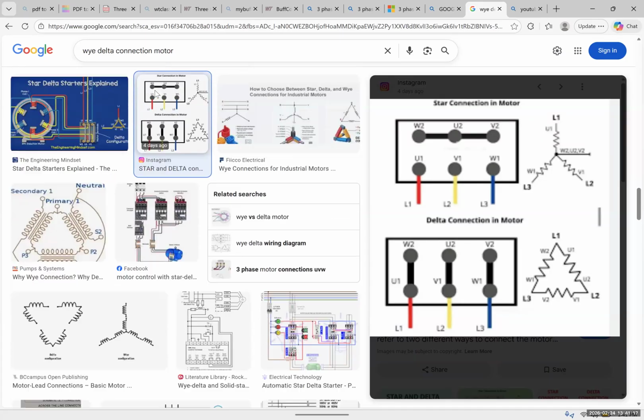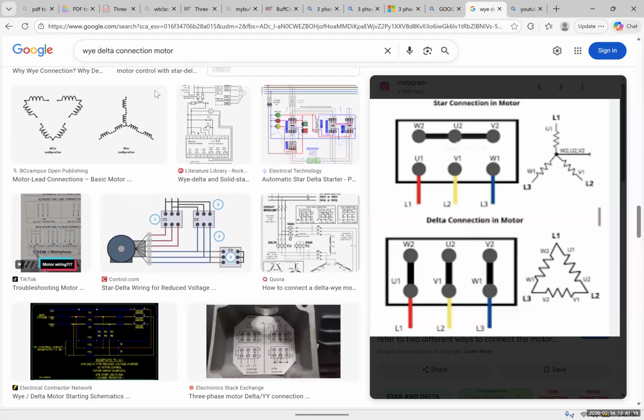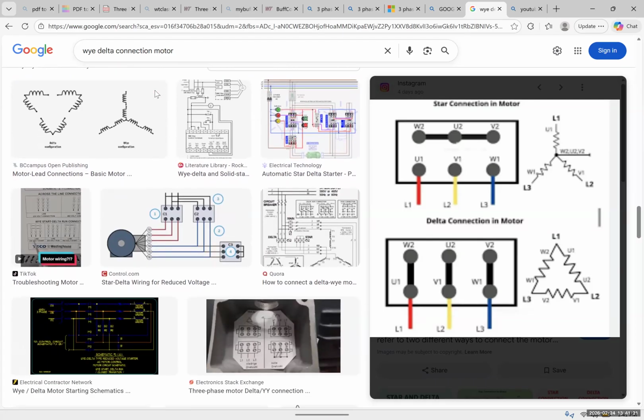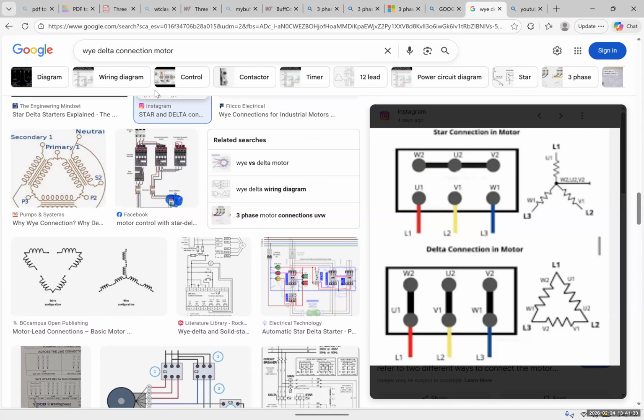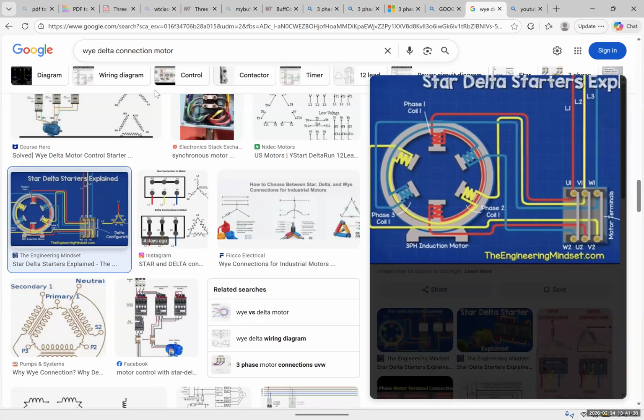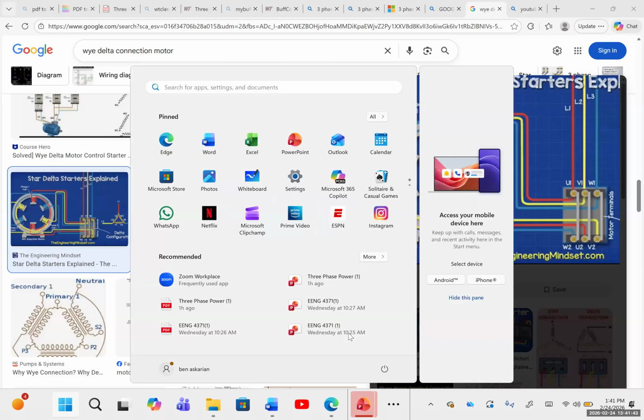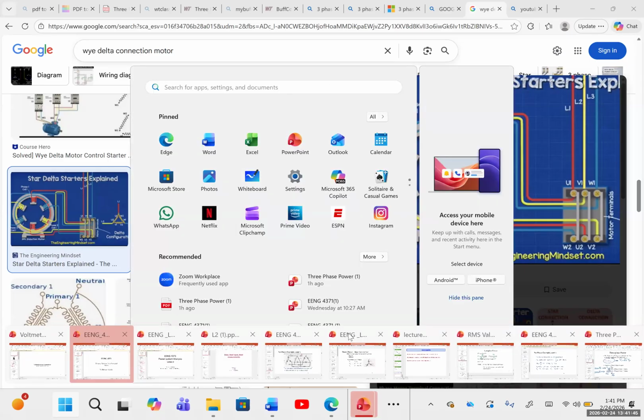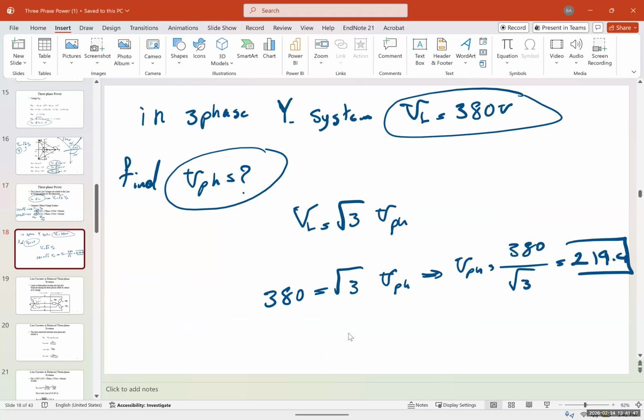But not all motors are capable of running both on delta and Y connection. These are specifically made motors, and these motors require 2 sets of wiring with an open end so you could connect it and configure it however you want. Most 3-phase motors, you're usually constrained to just run it on Y. And I'll explain Y and delta connection and what is the difference between them.